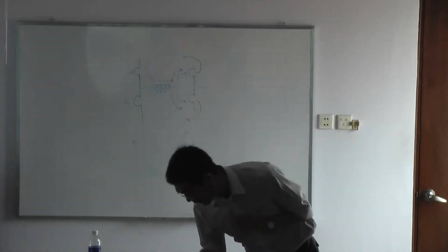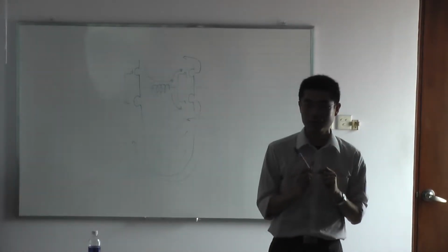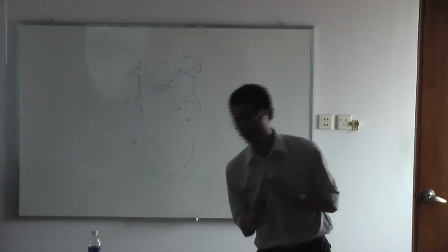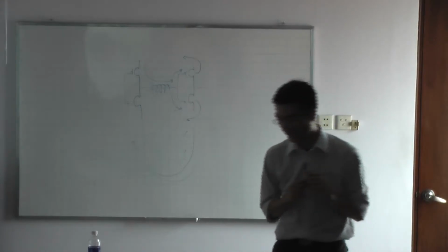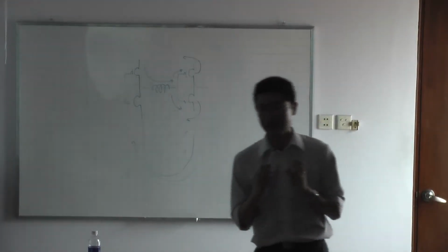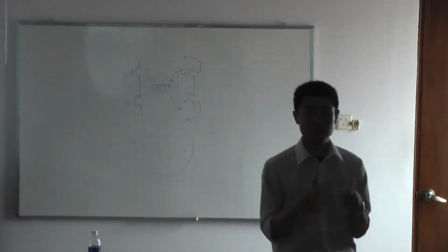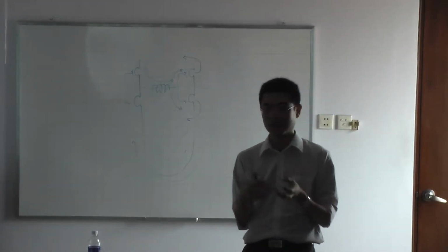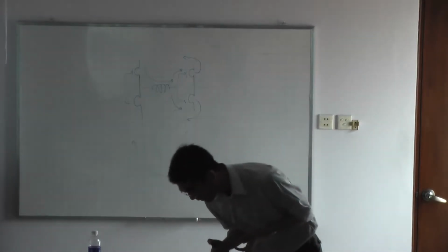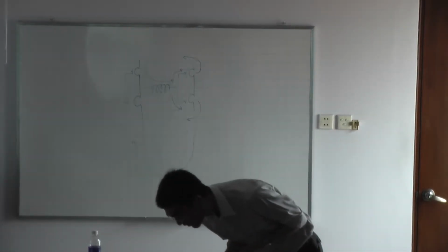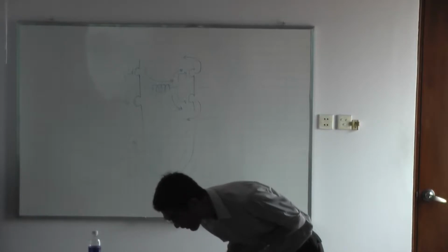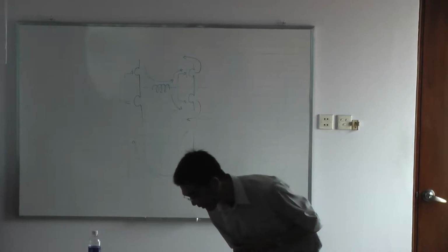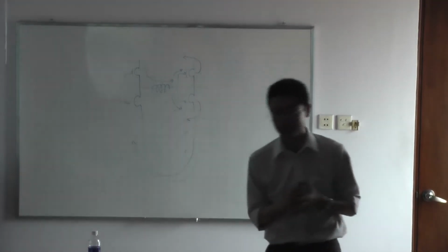And let's say we have resistors R1 to R3, and the input impedance Z0 should be 50 ohm. So once you decide the attenuation coefficient, you can calculate and find the resistor values we need. In this case, let's say for a minus 6 dB attenuator, its alpha value becomes 1/2.